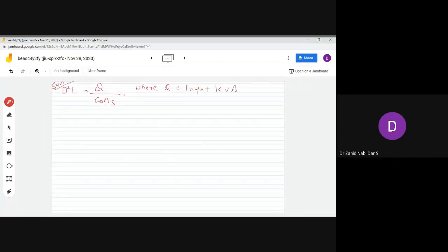So tell me the formula of Q in terms of kW. Q would be equal to kW divided by, yesterday also we did a problem, efficiency into cos phi. This would be kW divided by efficiency into power factor. So kW value you know is how much? 3.7.